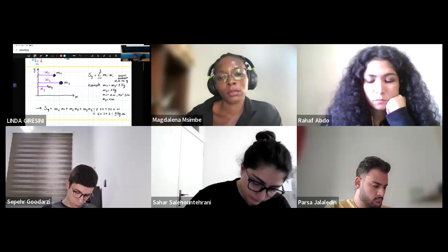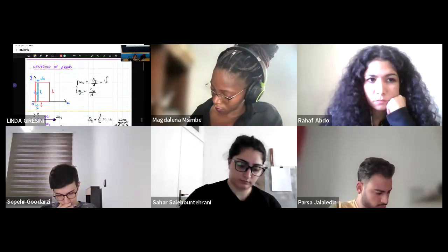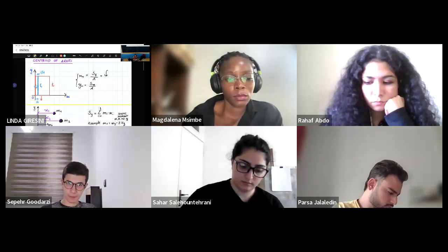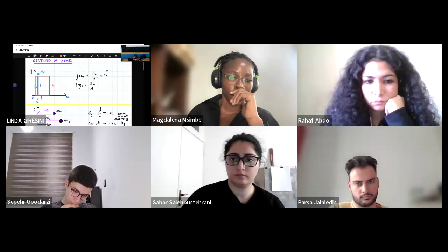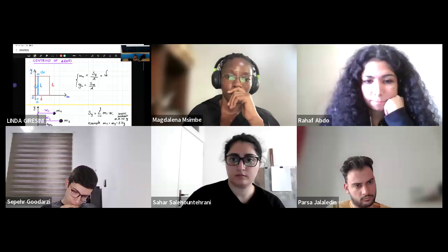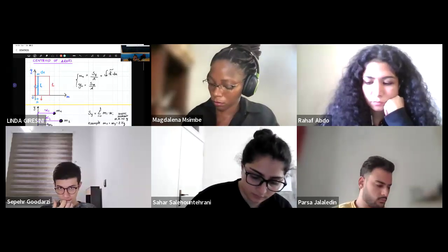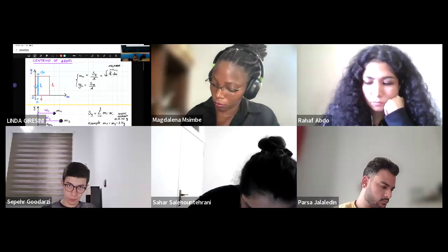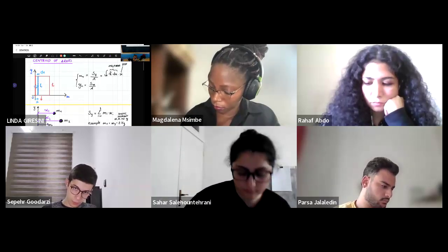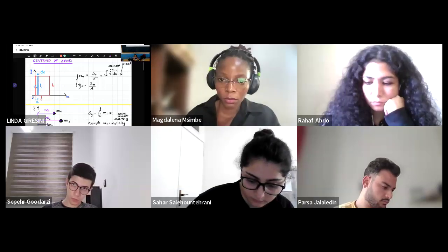The same concept is applied for geometrical shapes. So coming back to the rectangle, this time we don't have discrete areas. We have an area which is continuous. So the static moment will be each strip, the single area will be h times dx, times x, which is the distance from the y-axis. So it's absolutely the same.